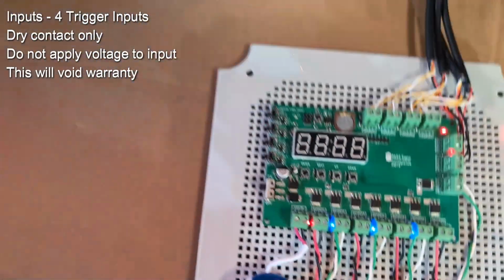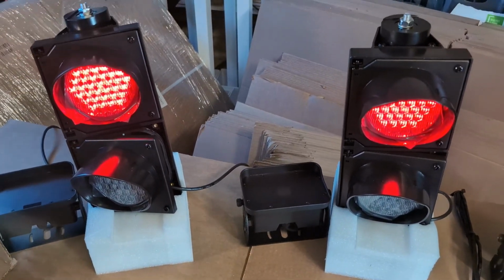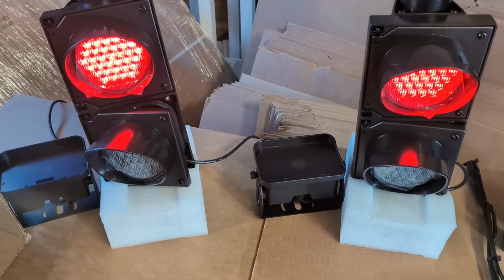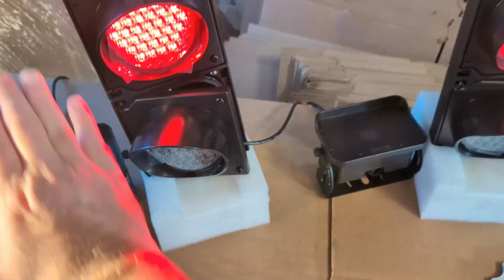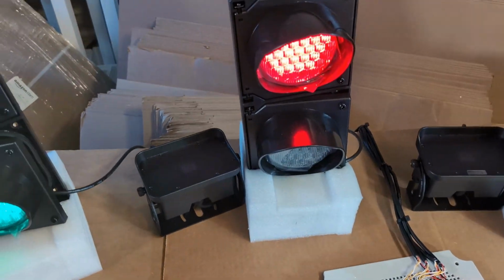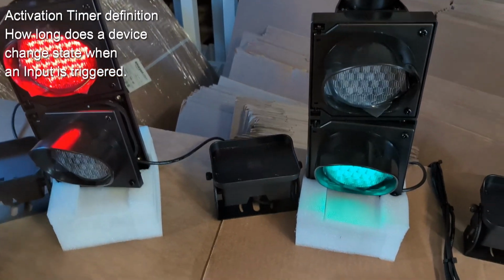Okay, so one of the things is say you have a corkscrew ramp and you're detecting vehicles coming down from the second or third floor, and the second floor obviously takes a little bit more time to come down than say the first floor. All right, so right now we have 5 seconds on that floor and 5 seconds on this floor. But I need 10 seconds to come down from the second floor.